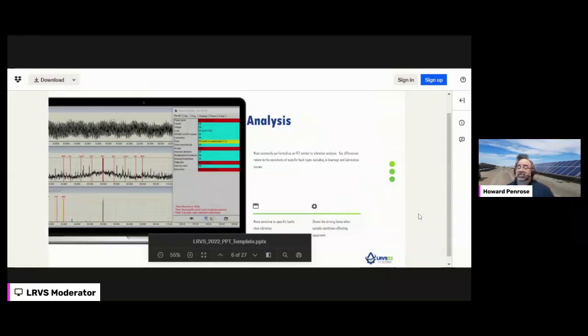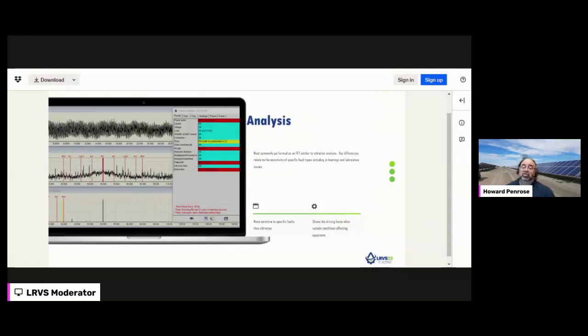The analysis, the best approach is an FFT analysis, which allows us to look at the spectra, just like in vibration. And then we convert that to decibels. There is a linear or demodulated spectra in virtually everybody's technology that you can look at, but it's completely useless for the analysis itself unless you are looking at a constant load across a period of time without any variation.